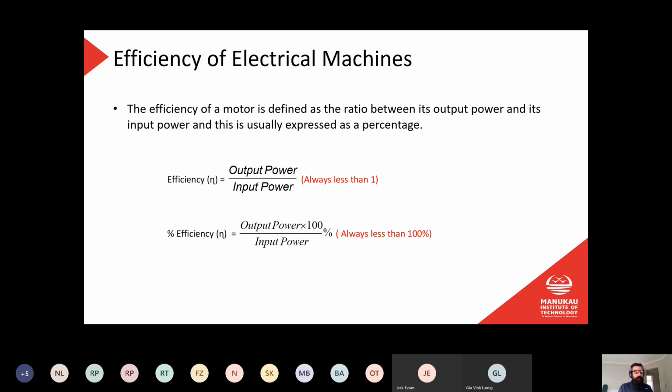When you look at an air conditioning machine, it gives you the same as what we're looking at here. It's got an amount of input power and then an amount of output power. On an air conditioner, the output power is obviously not the force generated by a motor like the example we're looking at here. It's talking about the heat energy output. The heat energy output is going to be greater than the electrical energy input for air conditioning and refrigeration in general. So how does that work? How can it have an efficiency greater than 1?